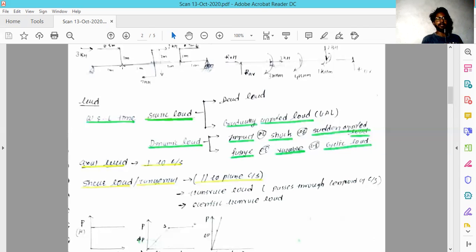So as you see, just to the right side of that beam, if you move 2 meter away from that hinge point, you will find two forces, which show a couple. A couple is nothing but forces of the same magnitude with different directions, separated by some distance. Here it is separated by 2 meter, and the forces act in opposite directions, each 2 kilonewton.